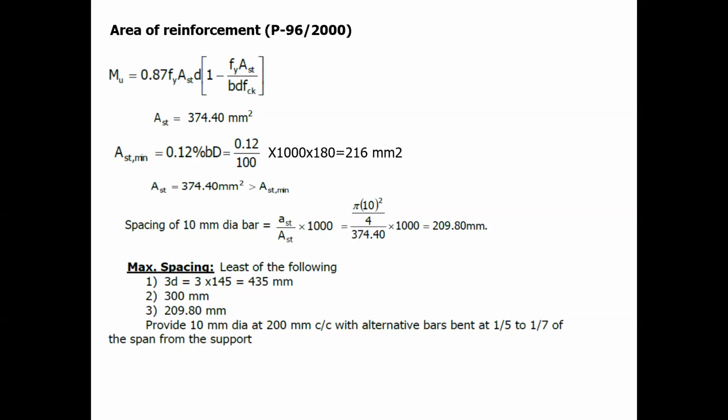bent-up bars at 1/5 to 1/7 the span of the support. In yesterday's class I showed how the alternate bent-up bar will look. Are you able to understand this condition? Or do you want me to show you in a figure? No, sir. Understood? Yes, sir.